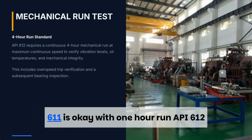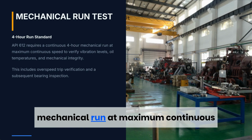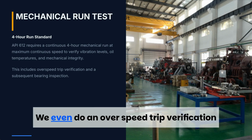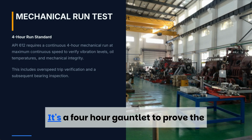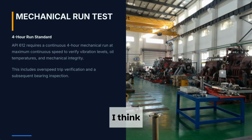While API 611 is okay with a 1 hour run, API 612 mandates a continuous 4 hour mechanical run at maximum continuous speed. We verify every vibration level and oil temperature. We even do an overspeed trip verification and a full bearing inspection afterward to make sure that there are zero hidden issues. It's a 4 hour gauntlet to prove the machine is ready for a decade of service.